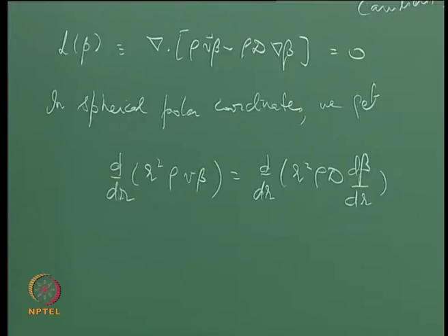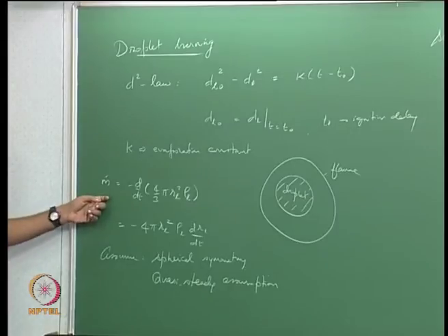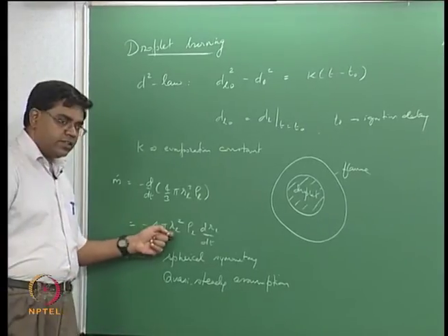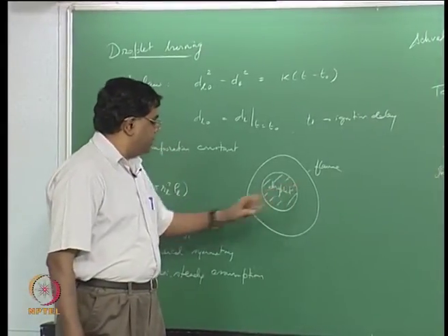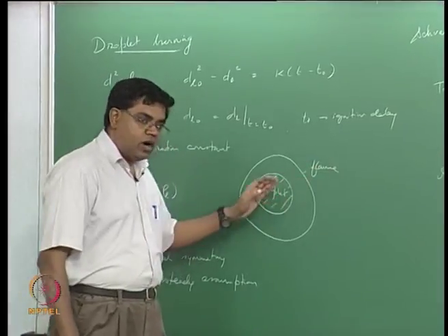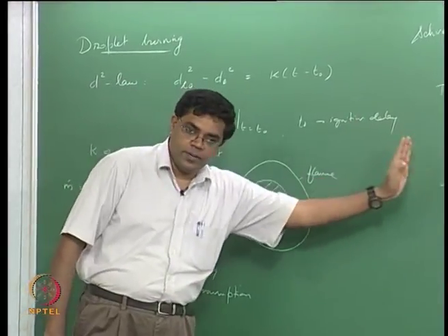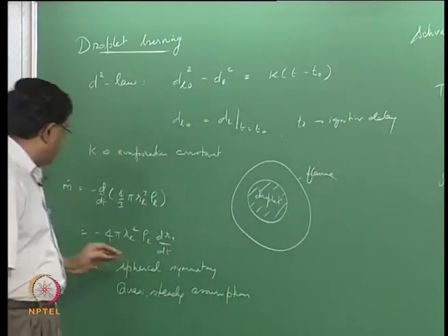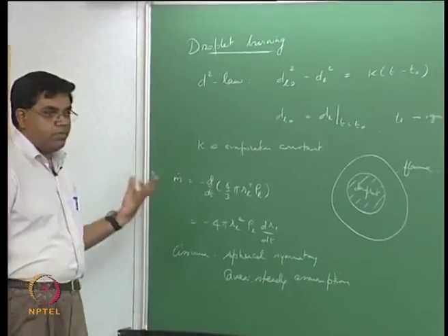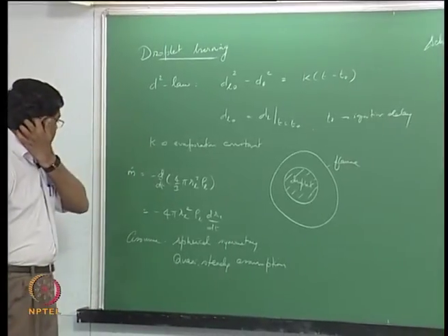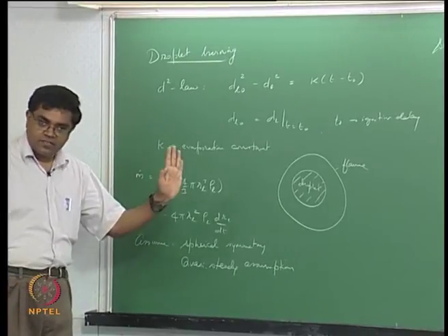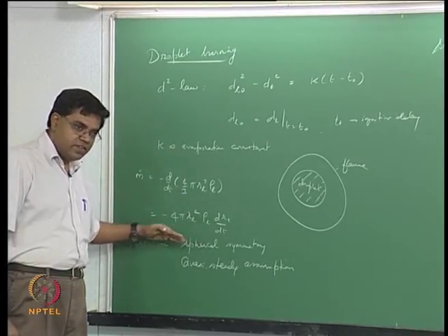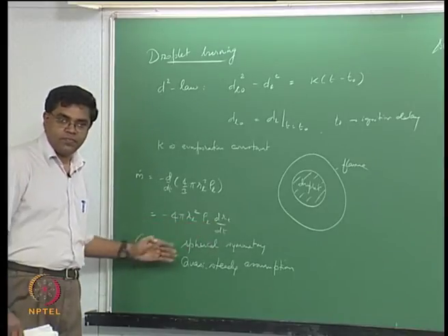Now we want to try to bring in this m dot, which will rope in our RL, which is the radius of the droplet at any particular time, to any radius. So r is going to vary from RL to infinity. m dot can be defined for any r, for the mass flux of the gas, but at the surface it has to match the liquid mass flux.